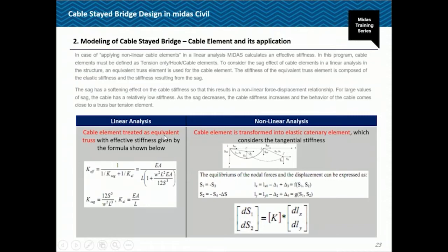So a cable element would be treated as an equivalent truss in a linear analysis, but it would be converted to an exact nonlinear elastic catenary element in a nonlinear analysis.